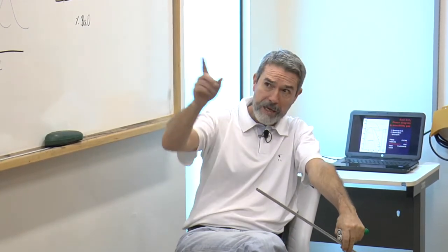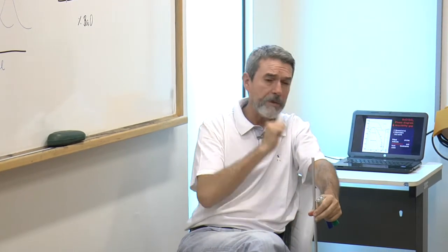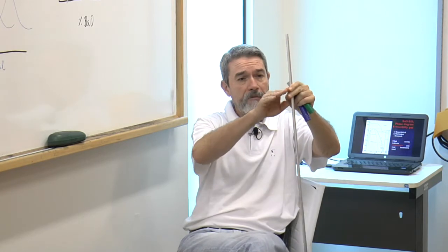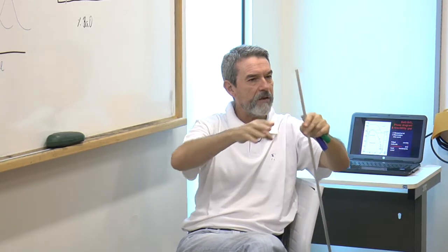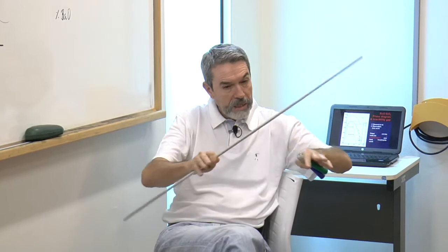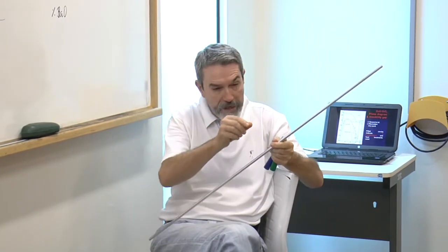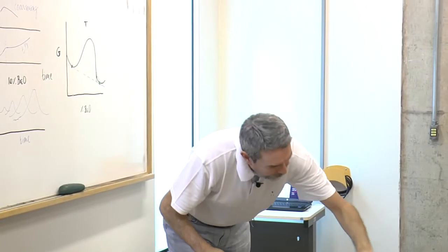Now, why is the mechanism of spinodal decomposition different? As I told you, in spinodal decomposition we have compositional fluctuations, but they evolve continuously. There is no nucleation of a phase with a completely, widely distinct chemical composition. It's just a regular evolution of two phases. And this can also be explained in the same figure.